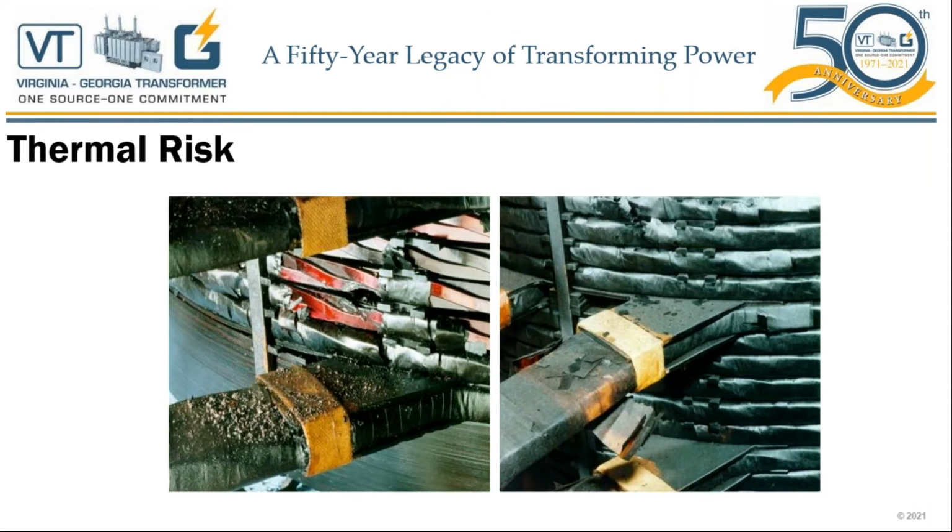I think in this slide, I don't really have to speak much. The picture speaks a thousand words, obviously, but these are some of the field failure pictures of extreme aging from thermal stress. This could be due to continuous overloading, not enough cooling of the transformers, and this can actually be due to fault currents not being stopped at the right timing of the failure. Because remember, the fault current multiplies by the reverse ratio of the impedance.